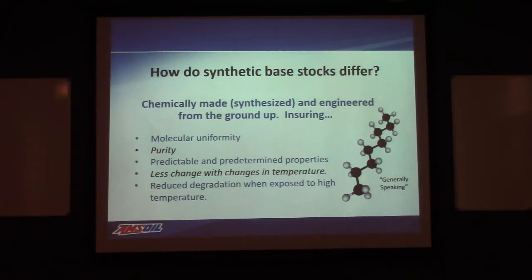Less change with change in temperature. Again, when we get back to the fundamentals of fluid lubrication, we all know that fluid lubricants, generally speaking, their thickness will change with changes in temperature. As they're heated up, they tend to thin down, and their load carrying ability decreases. As the temperature decreases, mineral oils will tend to thicken up.